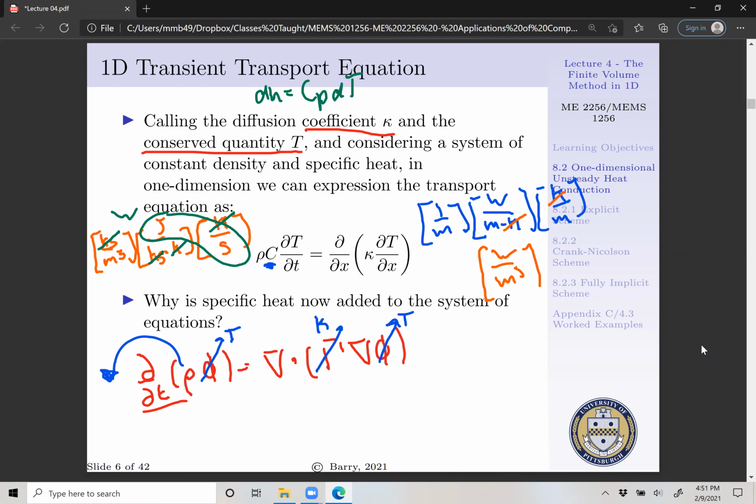So in addition to obeying homogeneity on the left and right hand side of our equation, we have to express this in terms of heat. We want to make sure that we're conserving heat, not temperature, within our system. So that's going to be the equation that we're going to cast in our finite volume form. Without C, units wouldn't make much sense, and when you write your code and run it, it would look hideous.